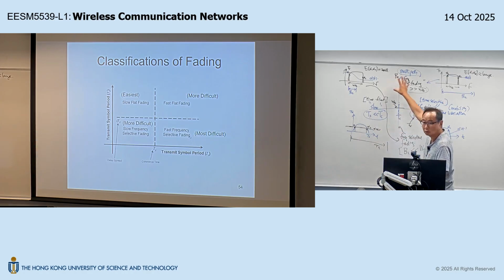So we build a channel model to model this multipath fading. Based on this channel modeling, we can partition into 4 situations. We need to first understand which situation we operate in before we attempt to design the transmitter and receiver, because these different styles of trouble have different impairments, and they demand different solution roadmaps. Once again, there is no universally optimal design that can work for all situations. If you are a good system engineer, you need to first understand your operating region.